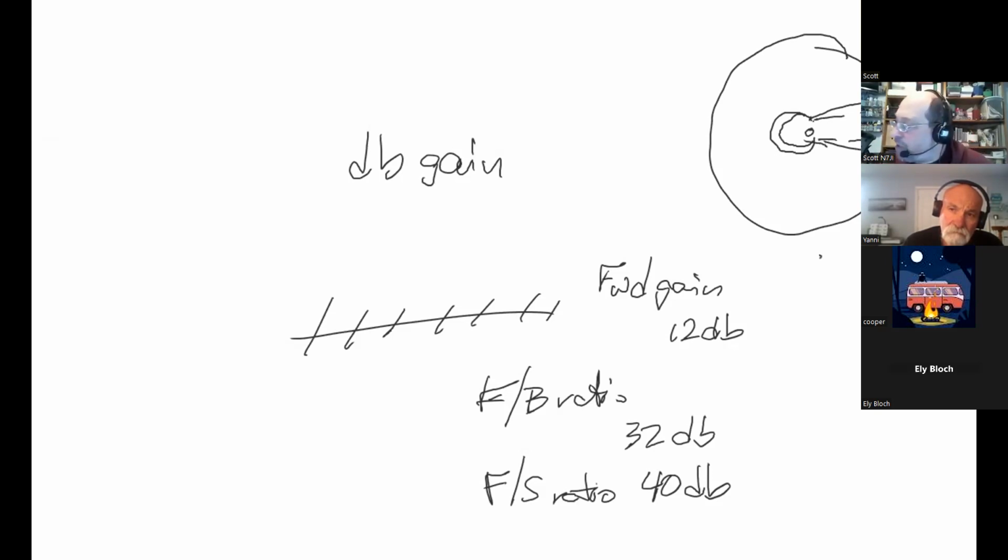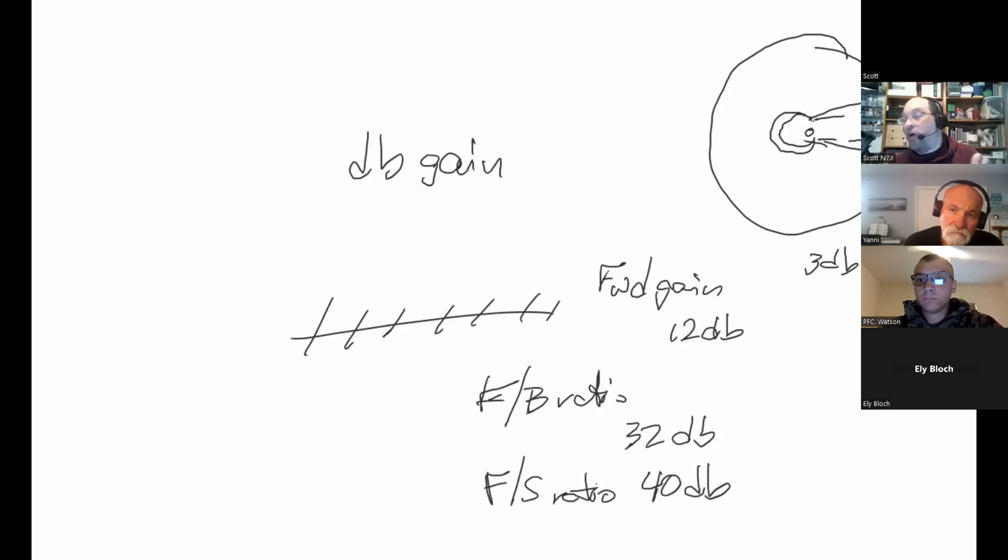And what is 3 dB equal to again? How much power? An increase like a double. Or down, 3 dB lower, that would be negative 3 dB. Oh, so I see. This is known as your 3 dB beam width, where your power is down 3 dB from the peak.